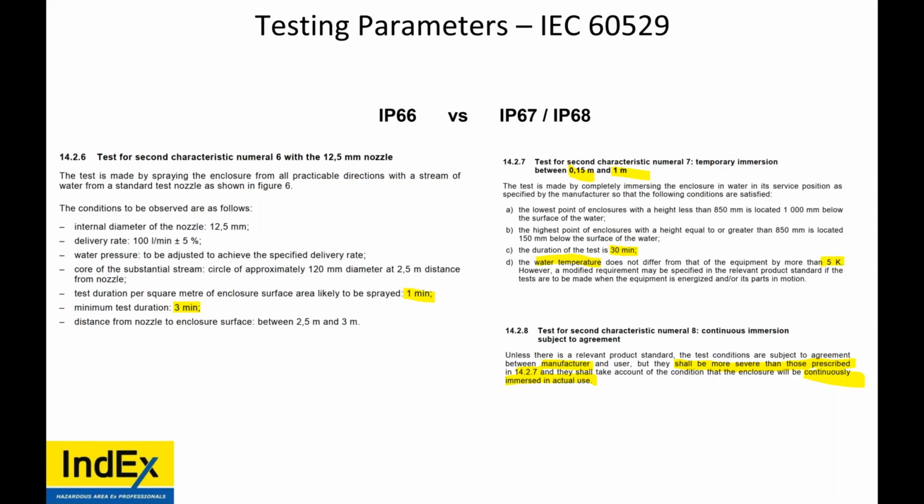It's just an extra add-on that the specifications or end user calls for, which protects their equipment from UV and lessens the chance of water ingress, because not all IP66 devices are going to survive, perhaps, 4 minutes of rain, 4 minutes of jets of water.